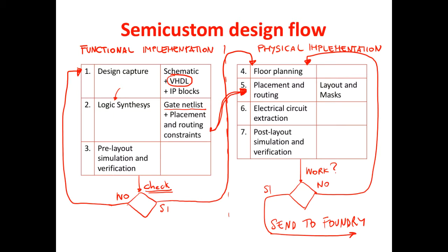This step is done, as I mentioned, quasi-automatically, in the sense that there are some software tools that do it, but then one typically needs to perform some adjustments because the constraints are not satisfied. But the nice thing is that once you have the placement and routing done, then you check the constraints via software, you see the constraints that are not satisfied, and then you work specifically only on those constraints. So the advantage of using the tools is that you can work on the exceptions. Most of the work is done automatically, and then you work manually on what is not working automatically.